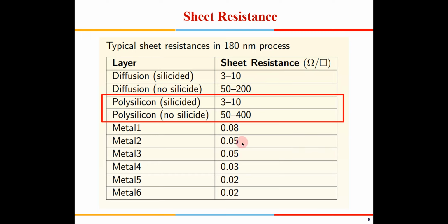itself. You can just extend it when one is kept over the other. So when the NMOS and PMOS are placed one over the other in CMOS and static CMOS circuits, they can be interconnected with a poly. And in a few places where two NMOS are placed adjacent to each other, you can make a small polysilicon interconnect.